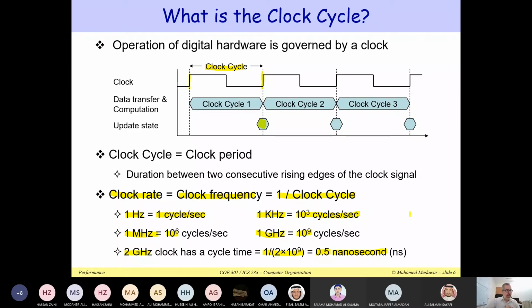This is not automatic by the hardware. It's going to increase the clock frequency dynamically. Now, there is one problem with increasing the clock frequency. The CPU will start consuming more energy per second. So therefore, it's going to increase the power consumption, and by increasing the power consumption, it's going to start heating. And therefore, it's going to increase its temperature. So at some point, the CPU cannot increase the clock frequency too much because the power consumption will be so high that a lot of heat will come out of the CPU, and this might damage the CPU.